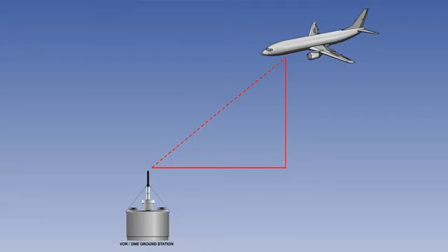The problem is easily solved by the use of Pythagoras' theorem. Let's consider an example. Say the height of the aircraft is 18,240 feet above the ground. If we divide the height by 6,080 feet, this gives us 3 nautical miles. Say the slant range is 5 nautical miles. This is a simple 3-4-5 triangle, and so the plan range is 4 nautical miles in this case.